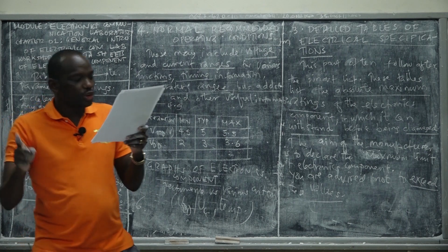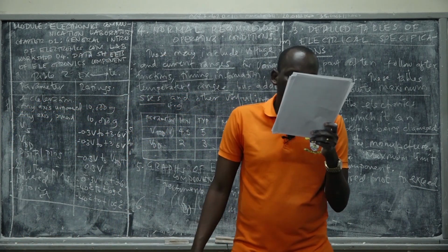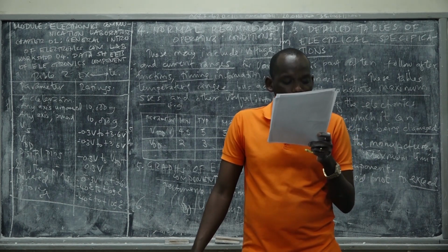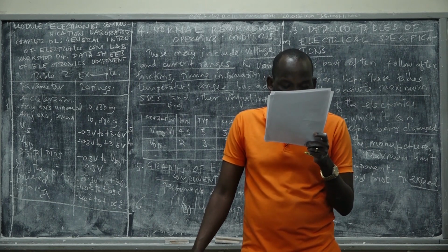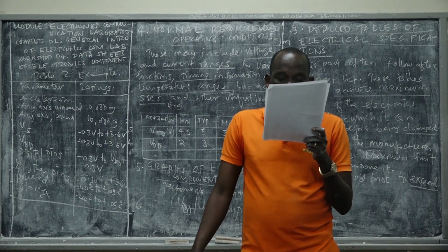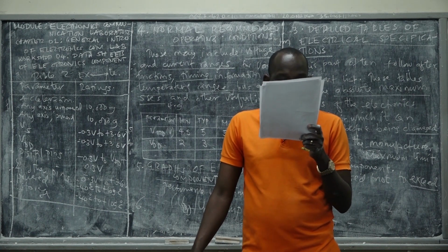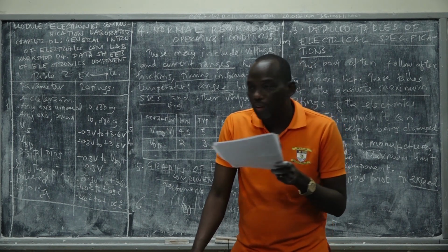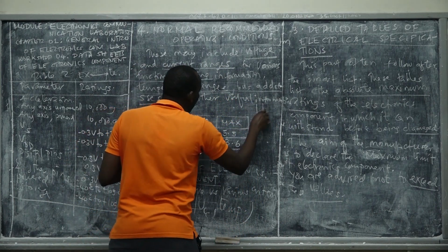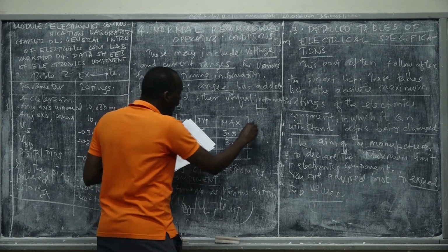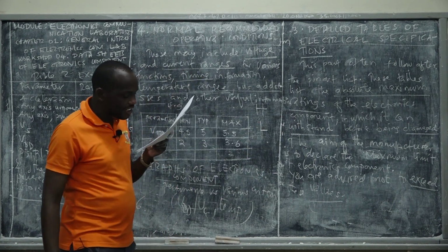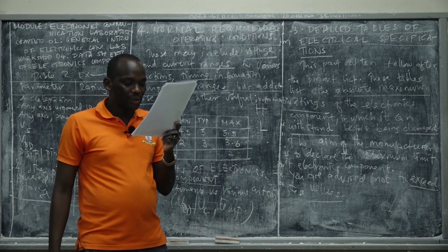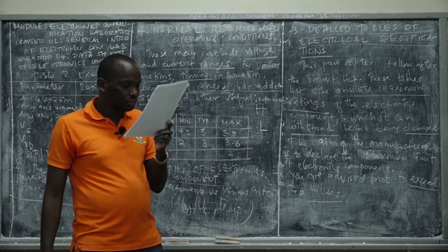So listen, truth tables show how changing the inputs to the part will affect its output. Each line has all the component's inputs set to specific states, and the resulting output of the part or electronics component. H means the input is logically high, usually VCC. L means logically low. The arrows mean that you should change the input, but we also have X. X means that the chip doesn't care what the input is.